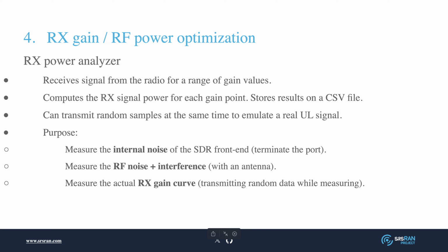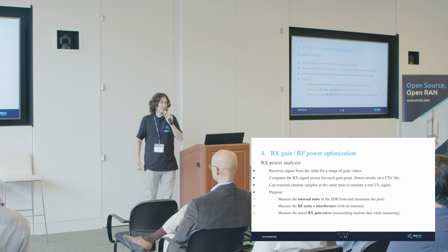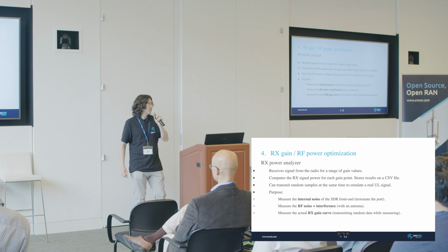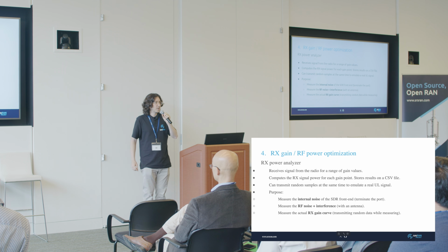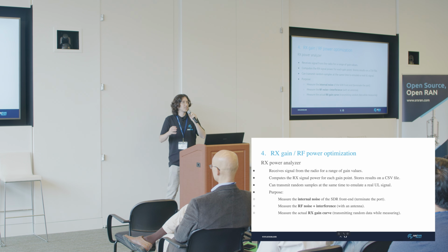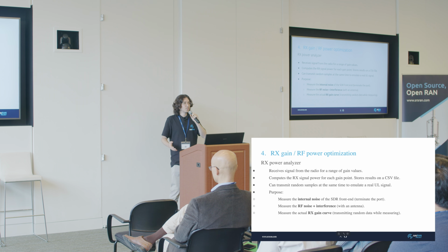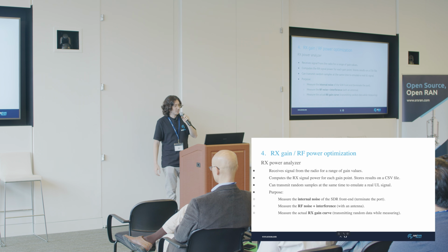Okay, now for the remaining of the talk, you are going to see some graphs with some measurements about noise. And I thought it's a useful moment for me to introduce a hidden little tool that we have in the srsRAN code base. We call this the RX Power Analyzer. This is a self-contained application that uses the same drivers that the gNB uses as far as radio is concerned. And it is useful to characterize the received noise that you see in a USRP.